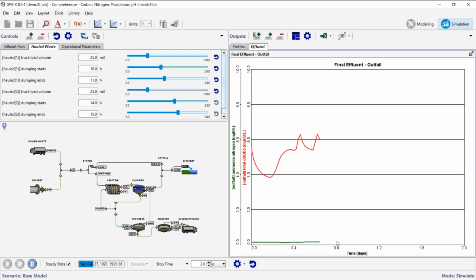You may have noticed, by the way, the ammonia is always in really good shape down here. So, all right, we're not exactly under 6 all the time, but most of the time. If you did a composite sample on this, it would be below 6. So that's not a problem. So it basically is a nice way to look at doing intermittent slugs of COD that might have an effect or bring some extra loading to your plant, and see how scheduling them at different points of the day can help out the situation.